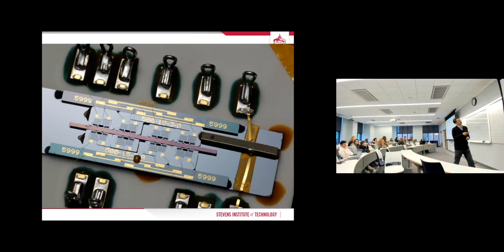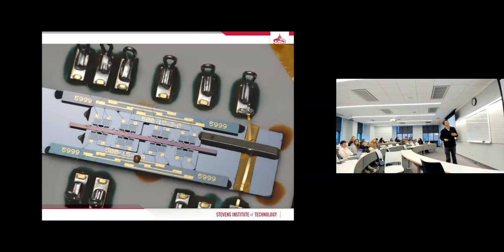So you have this bunch of these actuators. These are called CompDrive actuators, CompDrive, and you apply voltage, AC, then it moves like this because of the electrostatic force, okay? And there's a bunch of electrostatic actuators, and it opens and closes sequentially, like an inchworm, inchworm, so that this moves up and down. And that up and down motion gives the movement.